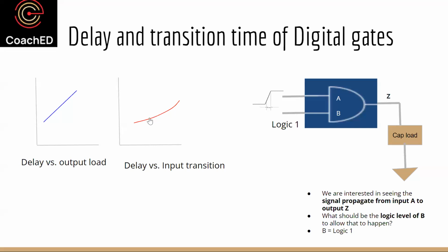So this depends on what kind of models you have. If it's a very simple model, you may not see this effect. Or if it's just an inverter, you may not see this effect so much. But if it's a complex gate, like an AND3 or a NOR3 or a NOR4, something like that, you may see this effect a lot more. So I will urge you to try this kind of simulation at your end and study it. One is how to run SPICE if you have not run it, or if you're interested in trying to run some basic characterization at your end.